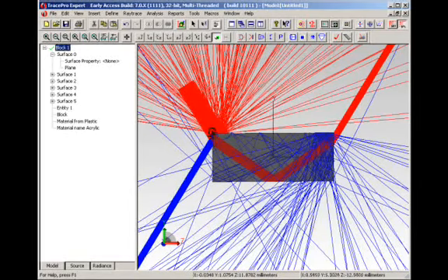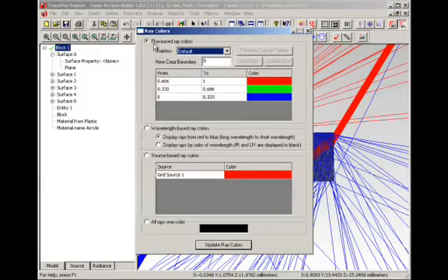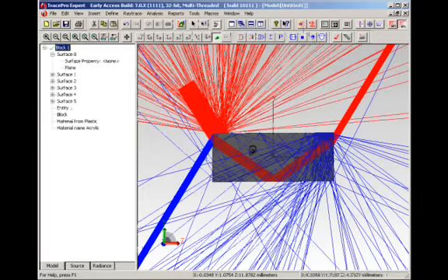But over here, we expect the light will then enter and bend, which it does for the red rays, but the blue rays are the low flux rays. In TracePro, underneath the ray color capability, underneath the analysis menu, we can see that rays are flux based. If they're hot rays, between 0.666 and 100% of their starting value, they're colored red. If they drop below 33%, they're colored blue. So sure enough, those are our TIR'd Fresnel lost rays. And so they're going to happen in several different locations. Over here, they're going to come back and hit on this particular top, and then they're also going to bounce until they finally exit the particular block.